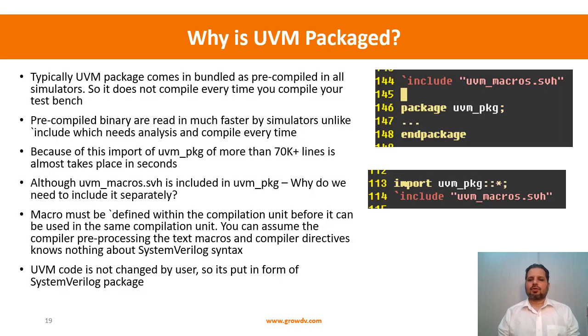So we have this question, why is UVM packaged, right? Whenever I want to use UVM, we will use these two lines. I will say import uvm_pkg::*, and then I'll say tick include uvm_macros.svh. So I get two questions. Why am I packaging? Although I understand after looking at the advantages of the package, I just want to make it clear. Why are we putting everything in UVM as a package? Why shouldn't I just do a tick include of the UVM code? That's the first question I have.